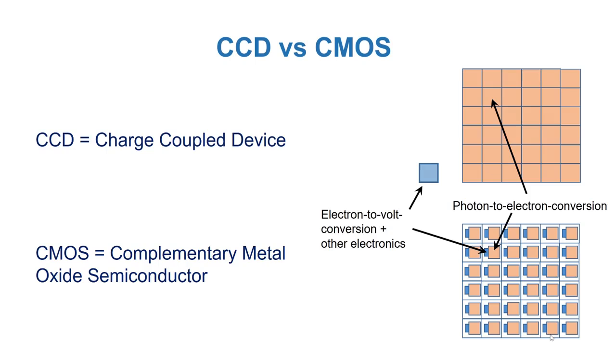In a few following slides, I will describe some aspects of vision sensors and comment on the differences between CCD and CMOS cameras for each. Note that the proportion of the surface area of each pixel that has photon-to-volt conversion in the CMOS is much lower than that of the CCD, which means that it will get fewer photons per pixel. However, this is often solved by adding a layer of micro lenses on top of the chip to gather basically all the light reaching the surface and use it as useful photons.